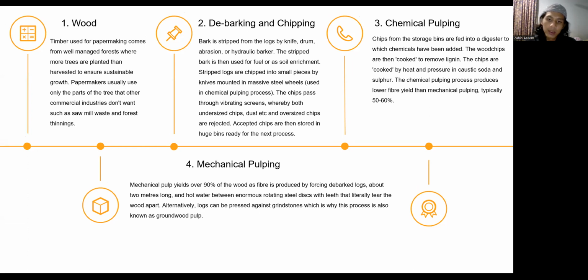So about the lignin, I will tell a little bit more. Trees contain up to 30% lignin, a material which is sensitive to light and degrades and turns brown in sunlight, which explains why paper made from mechanical pulp will discolor. An example of this is newsprint. Newsprint is designed to have a short lifespan, and if left for a long period of time will lose its whiteness and strength. But the special advantage of mechanical pulp is that it makes the paper opaque and bulky.